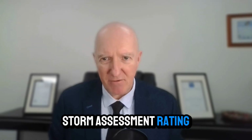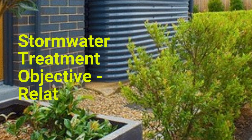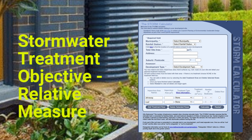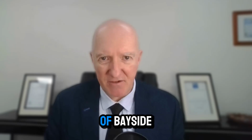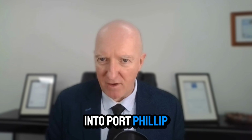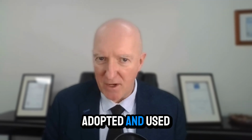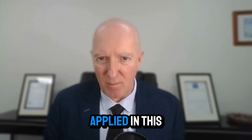A STORM assessment rating is required. STORM is an acronym for Stormwater Treatment Objective Relative Measure. This is a Melbourne Water online calculator designed as a method to simplify the analysis of stormwater treatment methods. It was created by the Association of Bayside Municipalities in 2004 to address the flow of water into Port Phillip Bay. Over time, it has been adopted and used by municipalities and is now formalized in Clause 55 as a tool applied in this standard.